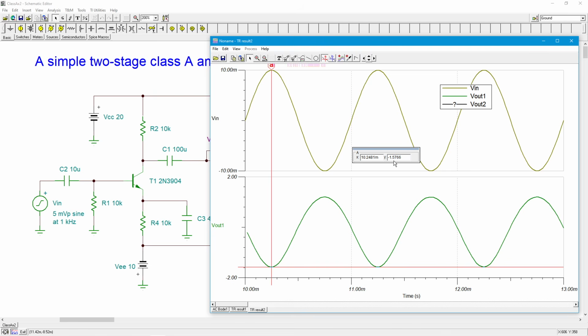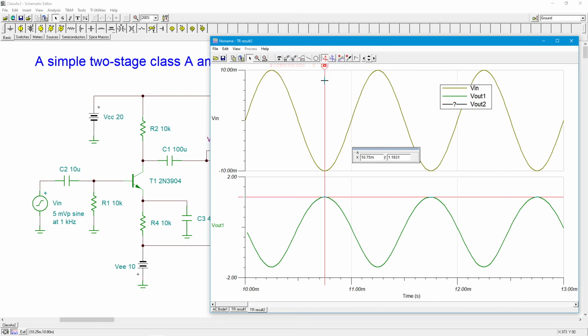Or in this case, you'd have to subtract off the 70 millivolts, in which case you'd be about 1.5. And up here, you'd add it on, right? And you still wouldn't even be at 1.3. So what looks like shifting is not just a DC shift. It really is because the waveform itself is distorted.